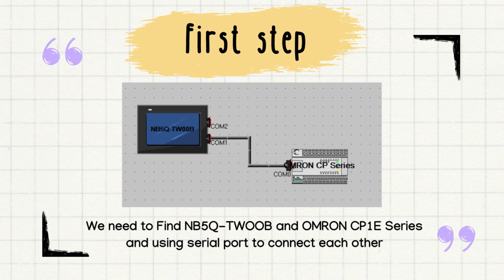For the first step, we use NB Designer. We need to find the LCD screen NB5Q TW00B and the Omron CP1E series, and use a serial port to connect them to each other.